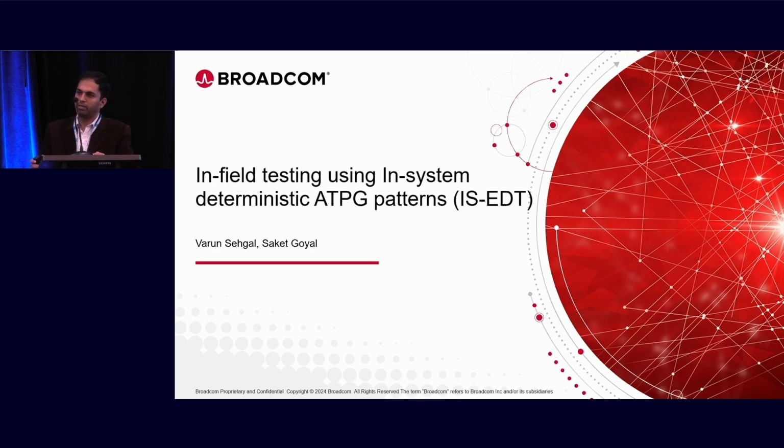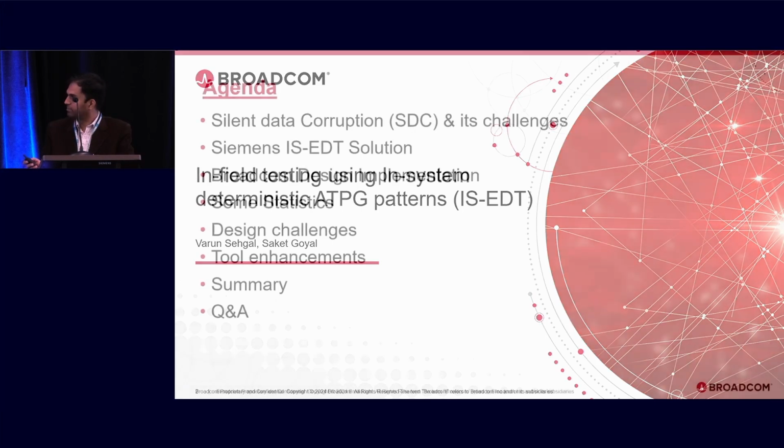But now we have been using in-system for a while; it's a very common thing. What is different here is that what we have been doing till now is in-system for JTAG, IJTAG and BIST related stuff. But what we are doing here is running deterministic patterns, that is EDT patterns, in the system. So that's what this is about, and I'll proceed.